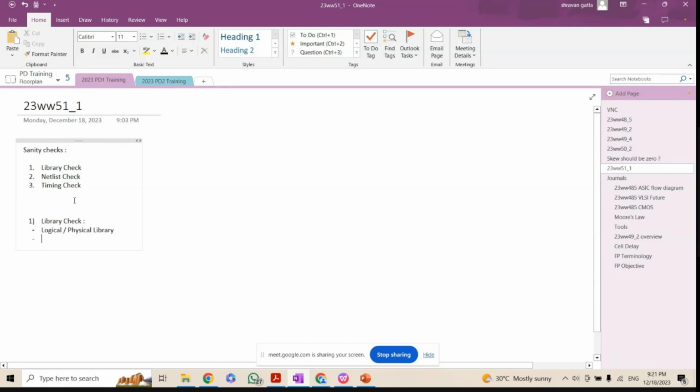You will dump the SPEF. Guys, do you understand this SPEF? SPEF is the extraction. It will contain the extraction details of your net. Let's say you have one buffer here and one buffer connected here. The SPEF tool, or the extraction tool, will break this net, convert it into resistance and capacitance, and calculate the delay values. That is what the extraction tool does. So we call this a SPEF. It will generate the SPEF and give it to the STA. STA will check that same path timing.